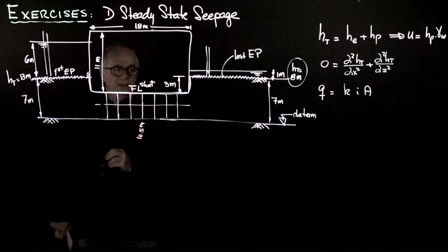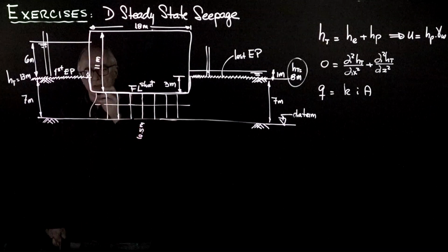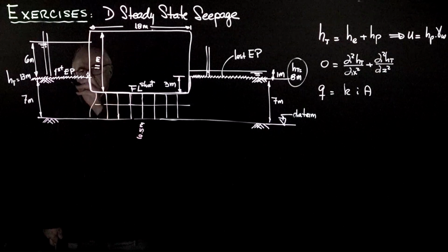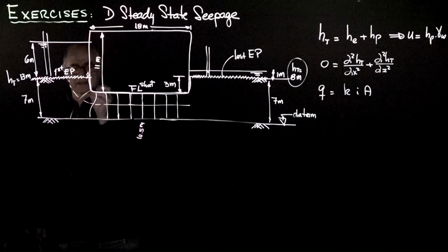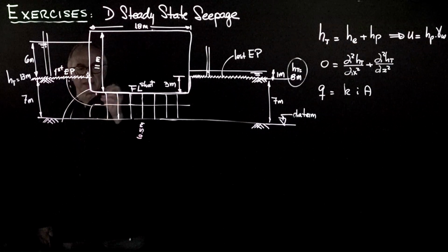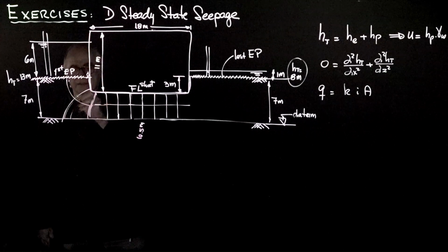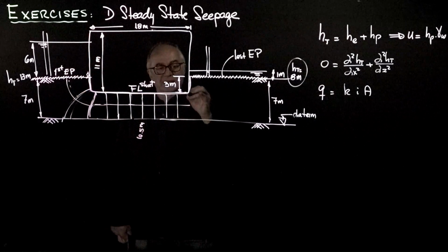And we are quite okay until we begin to reach the edge, because at that point it will have to begin opening up, because this is going to tilt. The idea is to migrate in that direction, but who knows exactly how we're going to get there. So if we go like that, this will have to go deeper. And let me not iterate anymore. This is not a pretty flow net, but it serves the purpose for this exercise. Please do a nicer version of that as you have time for another iteration.